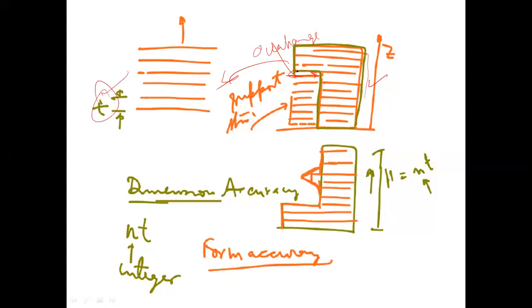Now, if you think that this overhang is not very significant to cause toppling, so when will the toppling happen? Anybody? When will the toppling happen? The toppling will actually happen when the moment of center is outside the body. So over here, it will not be outside, it will be inside.